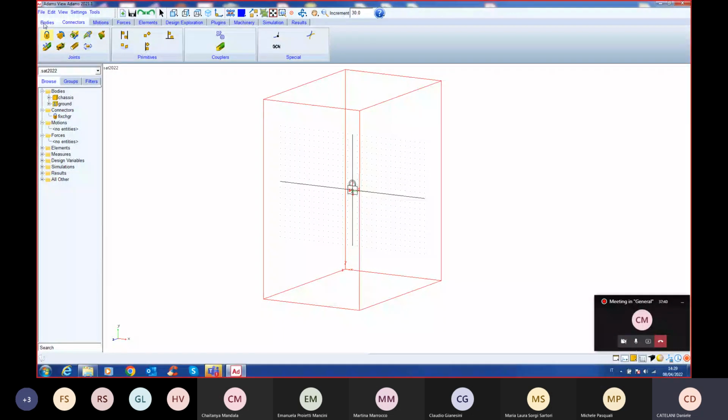So we can go to bodies, and we decide we need to locate the origin of the geometry of the body we want to create. To define an origin of a geometry, we can use specific construction elements like parametric points or like markers, which are points and which are reference systems, location and orientation. In this model, we will use markers.